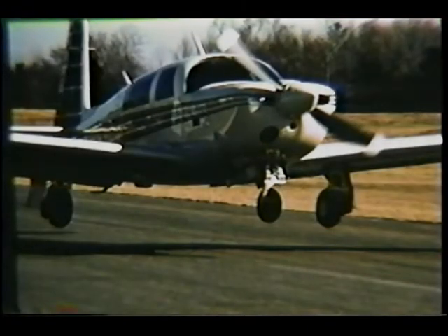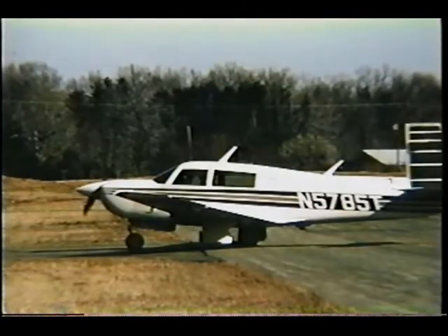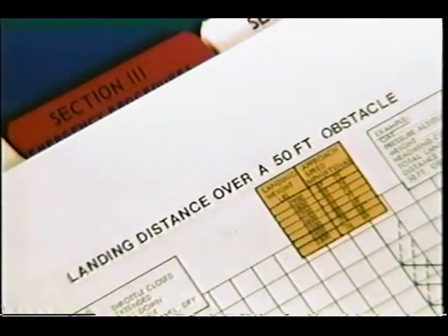And why are you still floating in ground effect? Because you came in light, at a lower landing weight, but you were still flying your approach based on VSO at max landing weight. So your airplane flew merrily down the runway. You see, your airplane's stall speed was lower because the plane was lighter, and your airplane floated in ground effect because it was still approaching its actual landing speed and just wasn't ready to land. The point we're making here is that 600 pounds can be just as significant a difference to a small plane as 100 tons can be to a heavy jet. And there you have another important lesson about landing, that you must learn and fly the appropriate approach speeds for different landing weights.